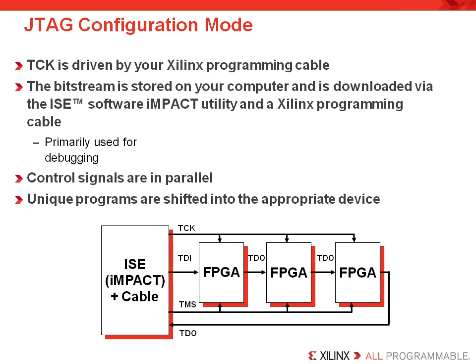After the JTAG mode has been identified by the FPGA, the JTAG pins become activated and the JTAG interface is used as a communication channel for the FPGA to be configured. This channel can also be used to create a boundary scan chain. The boundary scan logic is dedicated as part of each Xilinx FPGA and has all the mandatory elements to suit the IEEE standards. The JTAG mode allows the user to easily cascade any number of FPGAs into one chain for programming or debugging. JTAG mode allows a bitstream to be downloaded to each of the FPGAs in a chain with only a programming cable and a 4-pin JTAG header attached to a demo board.